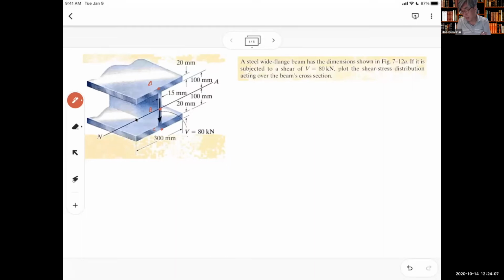And the reason is, as Jacob says, when we have a neutral axis, which is y equal to 0, then the bending stress is 0. So this is where your tau, shear stress, is a maximum, okay? Another thing you can find is this is not a rectangular cross-section, but an I cross-section, but still we have a maximum shear stress at the middle.